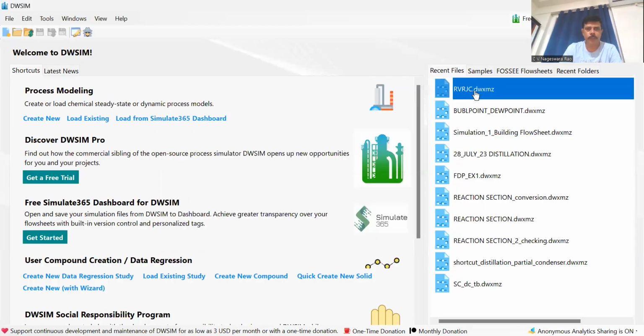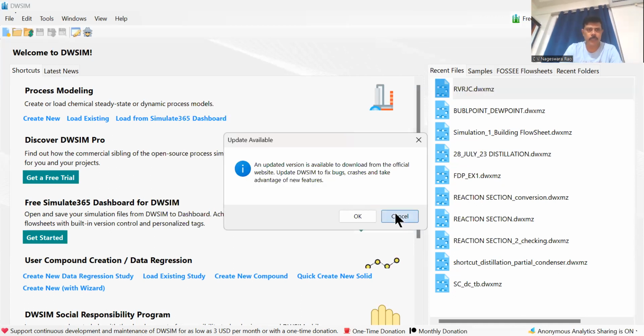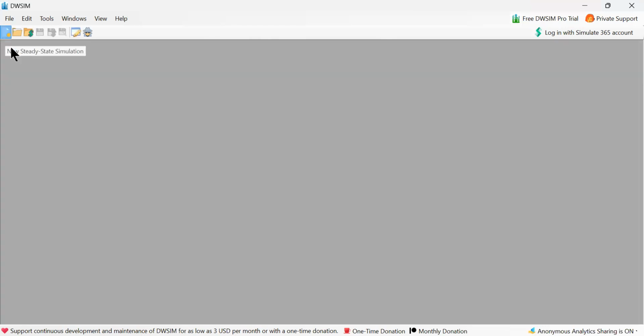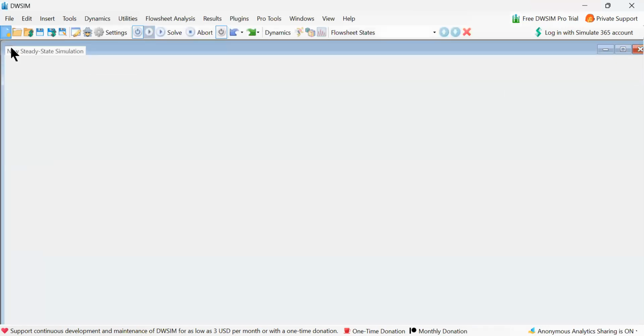Let me stop my video here. I'm saying I don't want the newest version. So this is the DWSIM platform. Let me create a new file. And as the problem said, now we are going to find bubble point pressure and dew point pressure for the system given: acetone, acetonitrile, nitromethane.